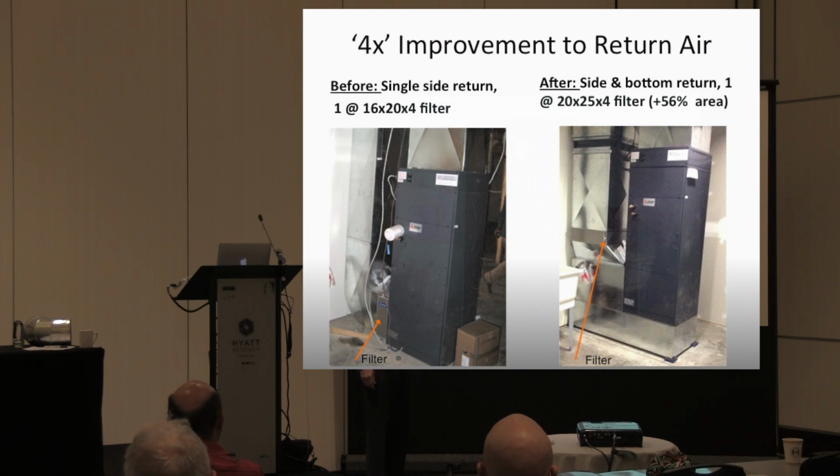What happens to the pressure drop of the filter? When it's clean, it's 4 times that which the manufacturers claimed it to be. Does it matter? If you sell doormats for filters, it matters not at all. The moment you upgrade to something that's actually doing some good for human respiratory particle sizes, this becomes a huge issue because the pressure drop is higher the finer you get, and this is completely destroying the ability of the filter to do its job, and you're causing its life to be shortened to perhaps a quarter or a tenth of its regular life. But it's even worse than that.